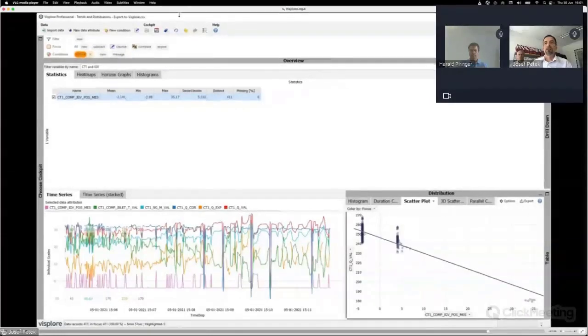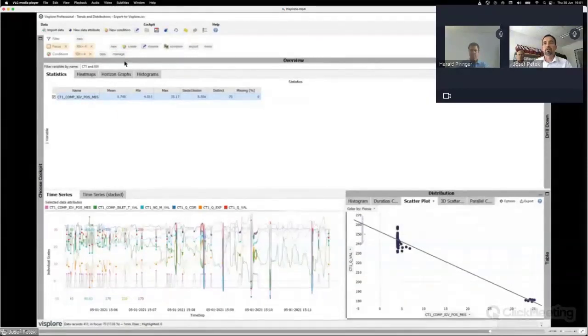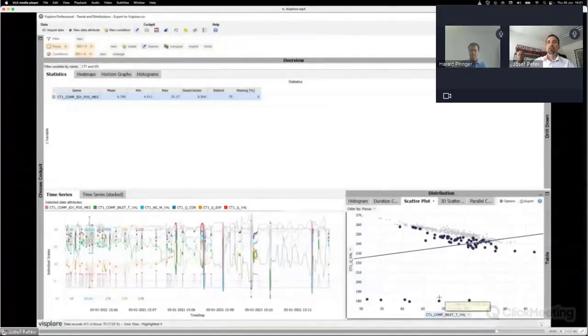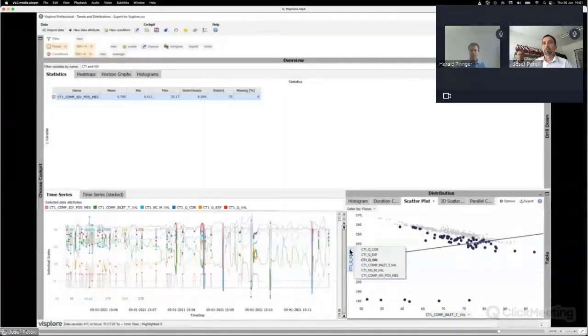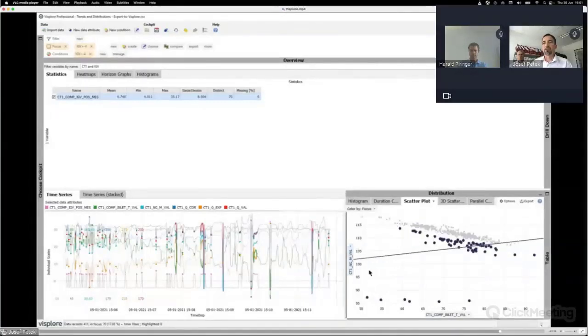And with that setting, I would now like to revisit the trends that we saw before based on ambient temperature, just to verify that selecting this IGV is going to prove that all the problematic data points are affected by the IGV setting. And as you can see here, this is the case for the fuel flow.